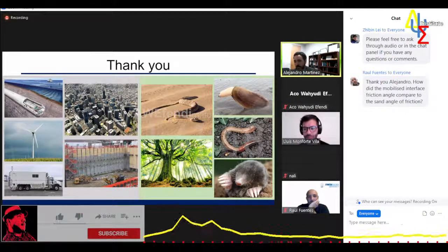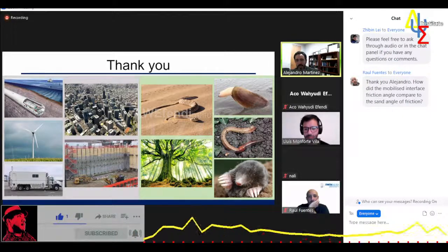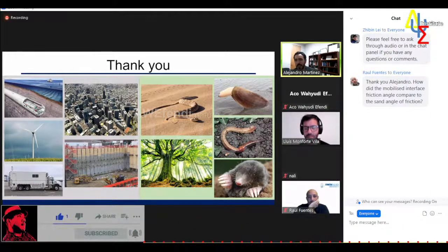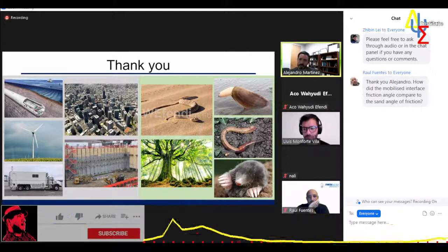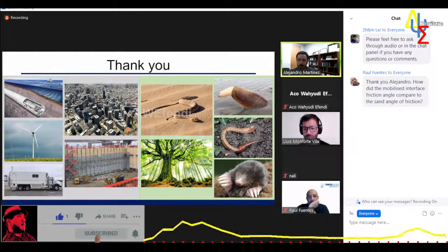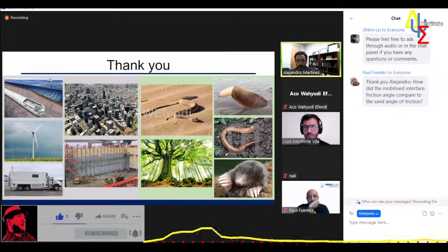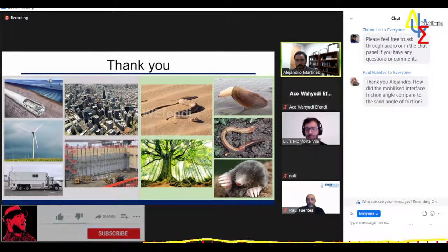Now, I think the dilatancy can be a little bit different. And so them having similar friction angles doesn't necessarily mean that they have the same strength, because in the field, the normal stresses depend on the dilatancy. And so we actually think we can force the soil to dilate more with these types of surfaces than with just a rough surface like concrete or something like that.